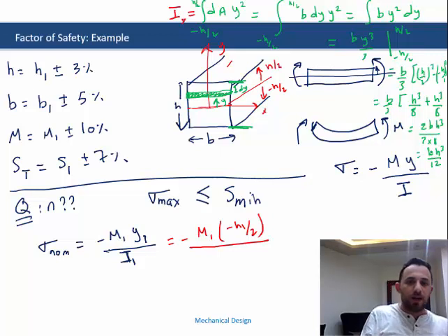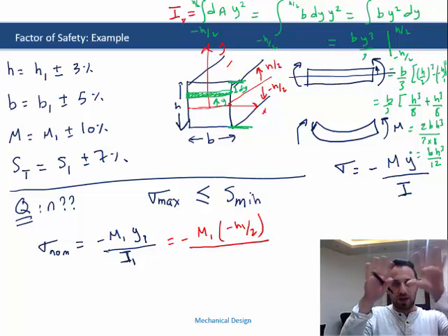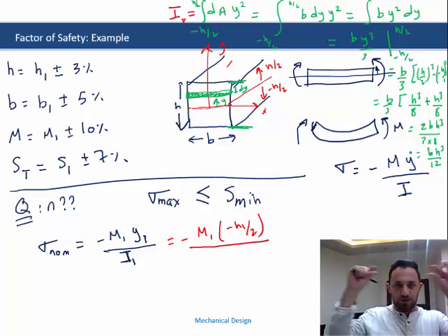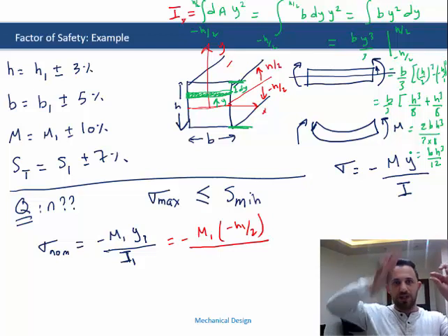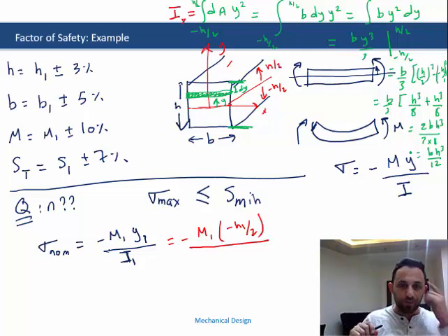Okay, the moment of area indicates how the area of the cross section is distributed relative to a particular axis. That's why we multiplied a small area. We need to see how the area is distributed around this axis. We multiplied the area of this strip, we take a small one, then we integrate over the whole cross section, multiplied by the distance y squared. All right.